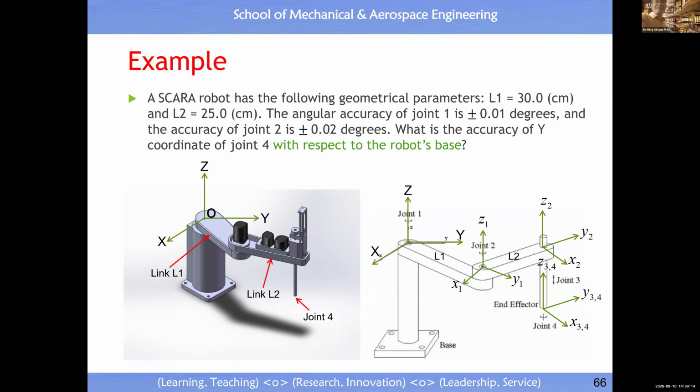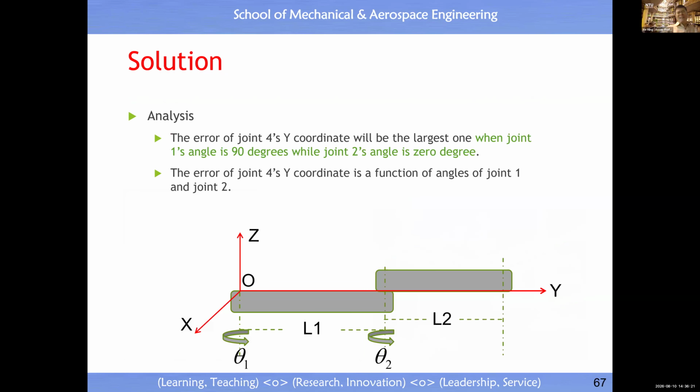So then this is a SCARA robot. We just look at the two links in the horizontal plane, L1, L2. Very simple mathematics, right? Theta 1 drives L1, L2. Theta 2 drives L2. Pay attention: theta 1 will drive the sub-assembly between L1, L2. Then theta 2 will drive L2 only, or eventually the sub-assembly after L2, if there is one. Interpret it in this way.